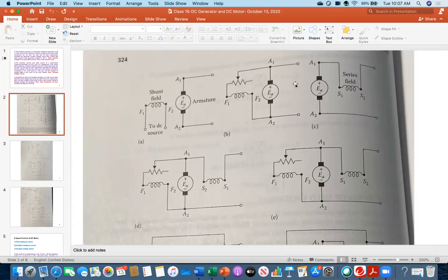And then label this one at the beginning, that is the VT. Because this is a motor, definitely the current direction will be from that dotted terminal towards the armature. That will be from the source, it will go towards the armature. That will be the current direction. And again, the armature is missing here, similar to the previous diagram. So everybody please put the armature between the armature terminal and the upper carbon brush. So this will be your DC shunt motor picture.